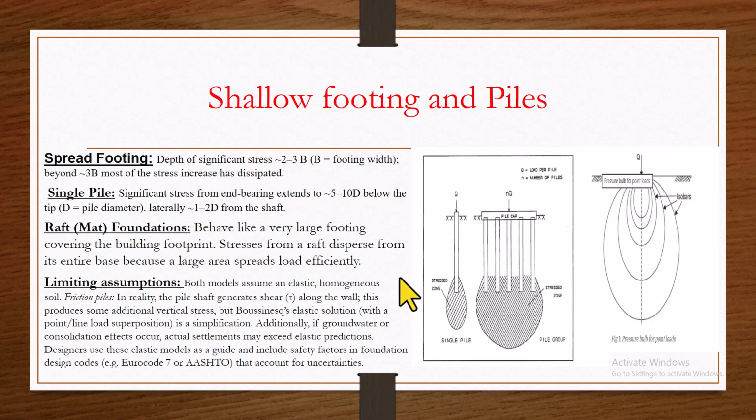The pressure isobars will begin to overlap, and once they overlap, it will reduce the pile capacity. That is why it is said that your pile spacing should not be less than 2.5, or not less than 2 according to some articles. It is always better not to go below 2.5, because you will be safer by taking 2.5. Let that be the minimum spacing of your piles.